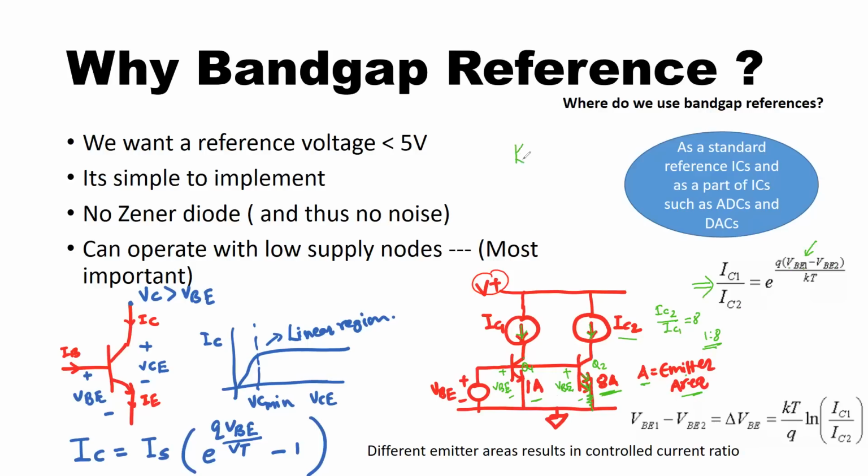So you have this transistor Q1, and then you have this transistor Q2, and the currents are coming like here, right here. And what you do here, you just have this resistor right here, R, and this is your ground terminal. So what you have here, you have VBE1, and then you have plus minus VBE2. And because of the different current densities in the transistors, you don't have the same current in the transistors,